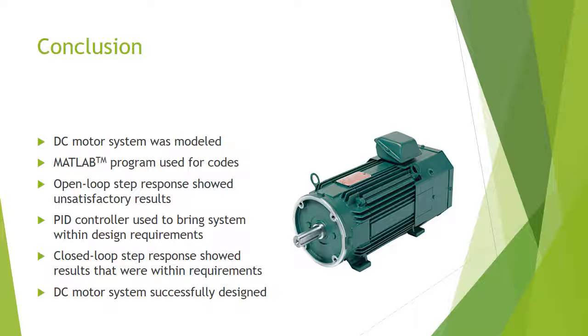In conclusion, the system for the DC motor was modeled. MATLAB was used with the root locus editor, the open loop step response, the closed loop step response, as well as steady state analysis. Since the open loop step response showed results that do not fit in the design requirements, I used the PID controller to get these within the requirements. With this, the closed loop step response showed results that were within these design requirements. Therefore, the motor system was successfully designed.